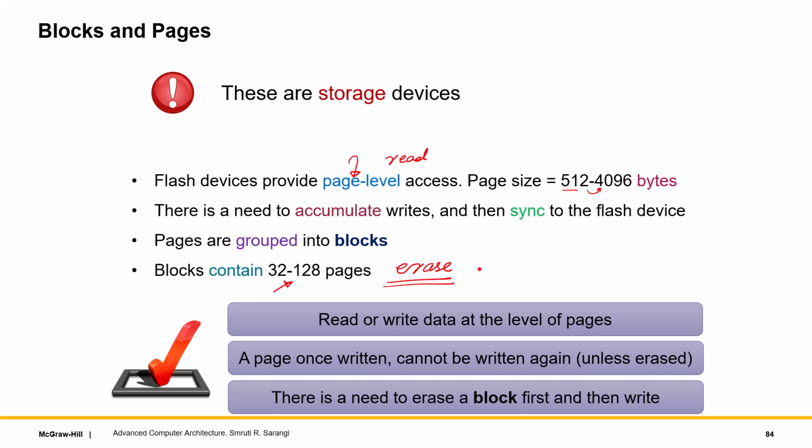So our storage densities can't be achieved. That is why we read at a slightly smaller granularity and write at a much larger granularity, because a write would involve erasing data. Erasing and programming are two different things. Erasing would mean a strong negative voltage, right? Programming, which is nothing but writing a 0, would be applying a positive voltage and pulling electrons up. So I've erased the ink.